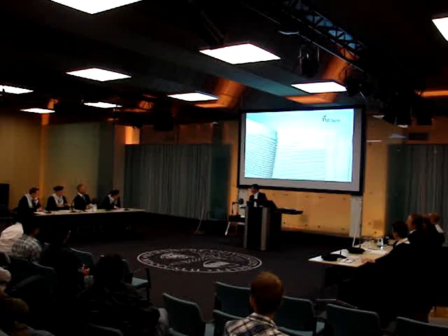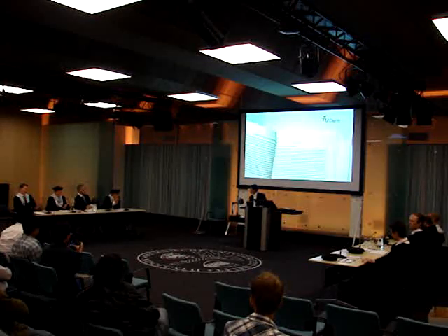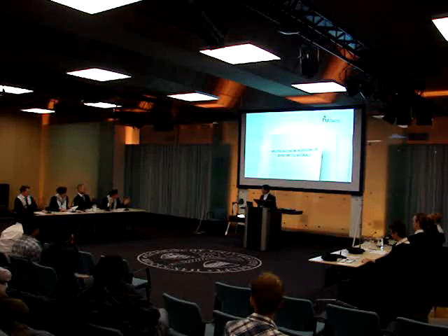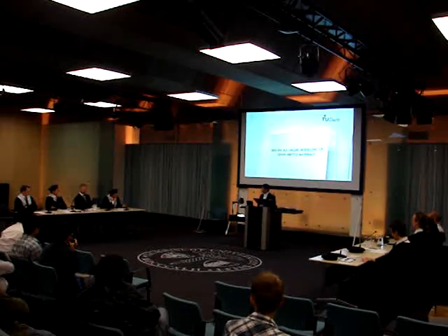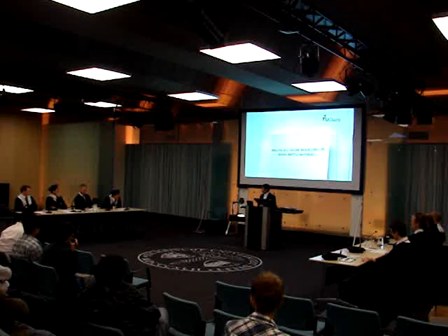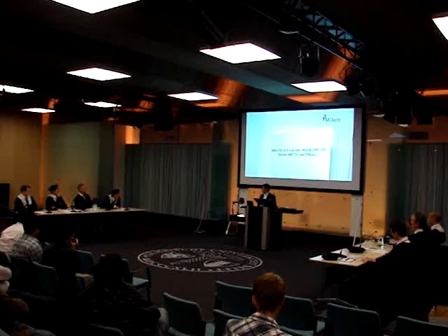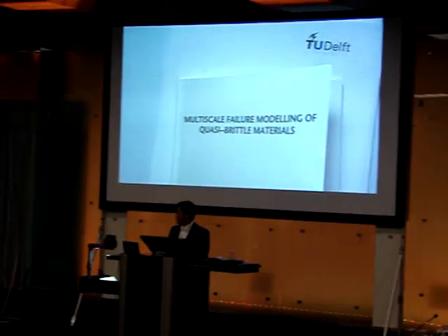But there's another parameter, this C. What does that mean? The C determines the width of the localization band. And referring to one of the previous questions also, what I can understand is when these micro cracks occur, it starts in a large volume, and then it probably reduces, and in the end you have a discrete crack where you can look right through, so it must be zero. So this C, I would expect it to be some function of the damage evolution, but you use a constant value. Can you explain why, and still you have very good results?